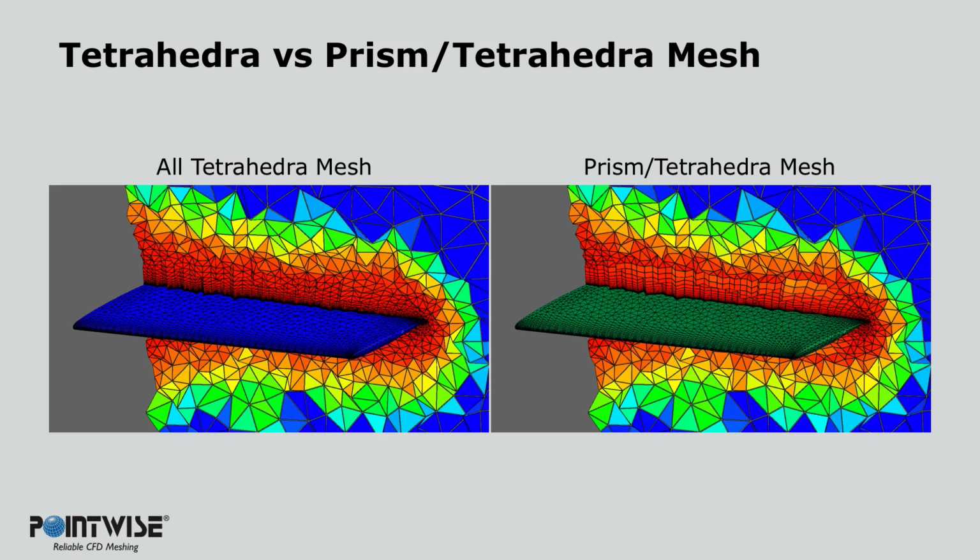Lastly, we were interested in whether the type of near-wall elements had any influence on convergence and accuracy of this process. So we repeated the mesh adaptation procedure twice. To investigate this, we exported two separate grids from Pointwise. The first grid was created using an all-tetrahedra mesh, and the second grid utilizes Pointwise's T-Rex cell combination feature to combine the anisotropic tetrahedra of the first grid into prisms without modifying any of the isotropic tetrahedra in the far field.